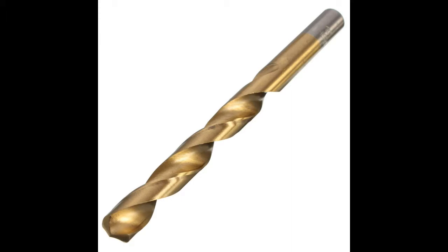But you do need to account for that drill tip, because the drawing depth for a hole is to the shoulder, which is the edge where the tip starts, and so you need a full diameter minimum to what the drawing says, plus the tip, unless there's special notes on the drawing.